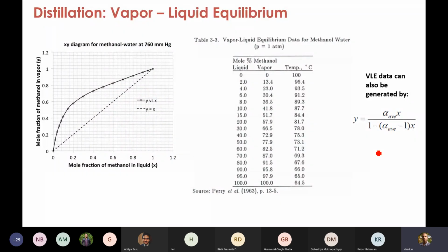For example, if I am separating a mixture of methanol and water, I must know the vapor liquid equilibrium for this methanol and water system, because ideally, if the tray behaves ideally in bringing the liquid phase and vapor phase into equilibrium, the vapor phase will escape a particular tray and the liquid phase will also escape that tray after mass exchange. If equilibrium was established, these two streams will be in equilibrium with each other.